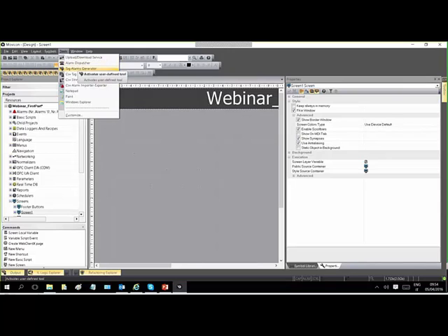Then the other windows are the Script Explorer. Movicon 11 keeps on board the WinWrap library, so when necessary, you can extend the functionality through Visual Basic code that could be added in a different project context as a resource, for example, to initialize variables inside a screen when the screen is loaded. We'll talk about scripting in the intermediate level.